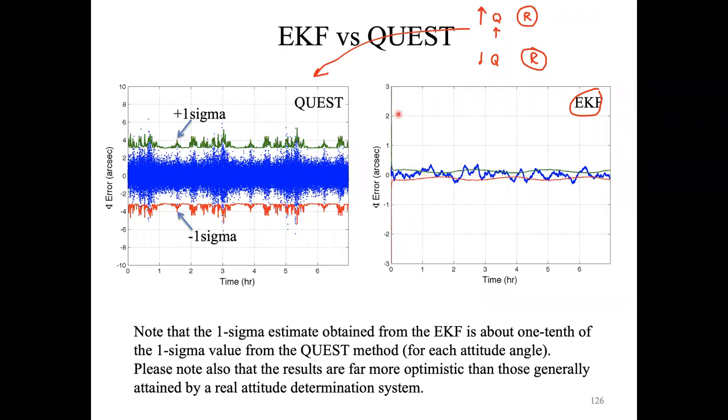The other question was regarding the process noise and the measurement error covariance. As I said, these two metrics are related to the error measurement of the star trackers or the other sensors like Earth sensors or sun sensors. And the Q is related to the errors of the quaternions. If you want to see it in a similar way to the orbit determination problem, yes, the inverse of that sigma squared could be seen as the weight of your observation. So that was the question.